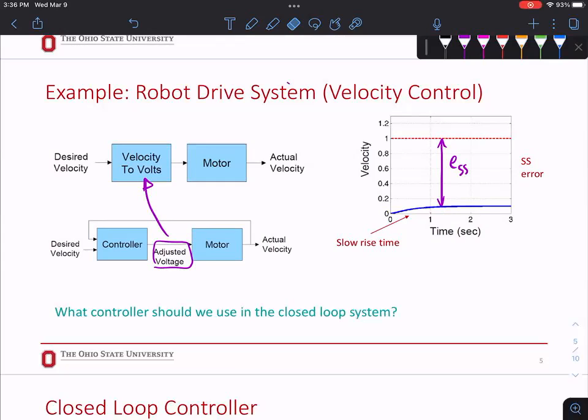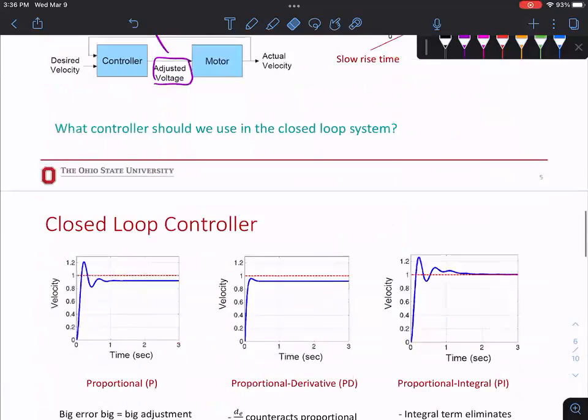Now, to get rid of oscillation, we can adjust our KP, or if we couldn't, we have to add the derivative, which has the damping. So if you couldn't use P and I together to get rid of the problem, you add D. So the subsets of the PID controller are the PI controller, PD controller, PID controller, or just a P controller. Sometimes it's just a gain, and we solve some of the problems with just a P controller.